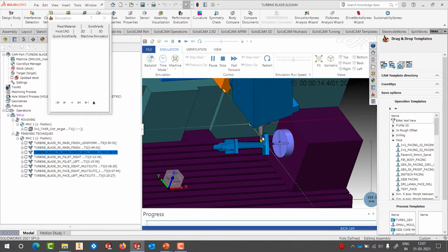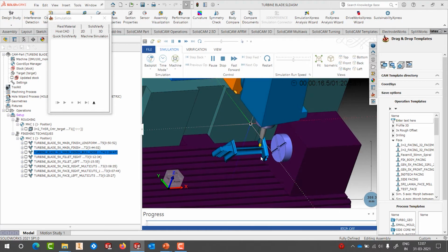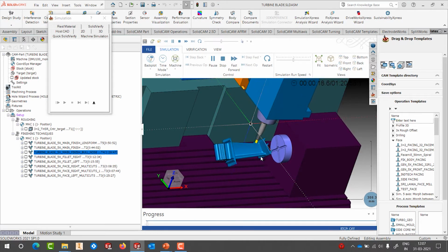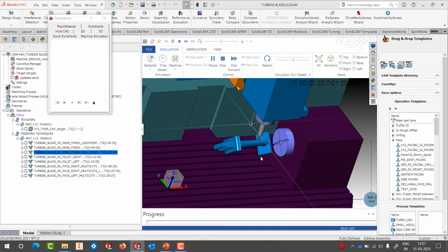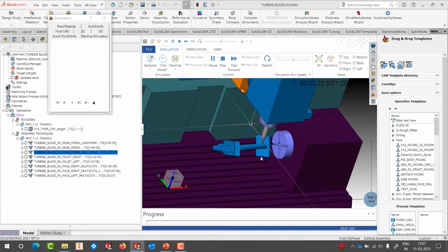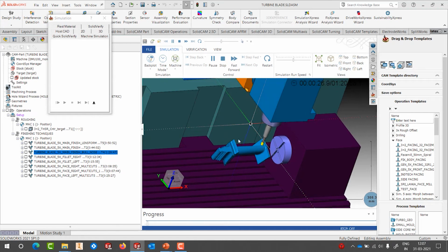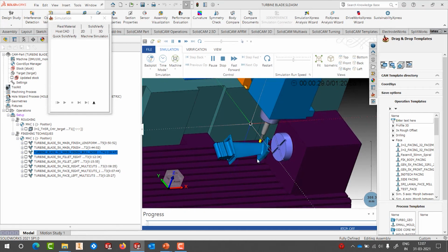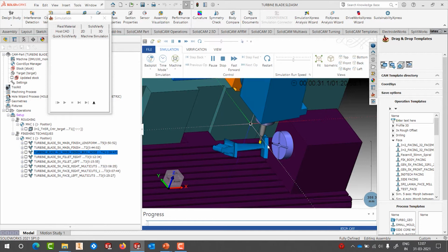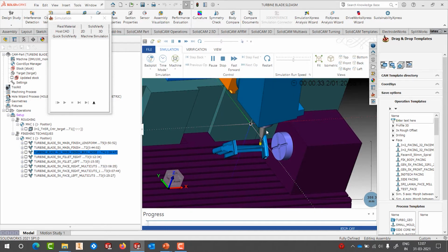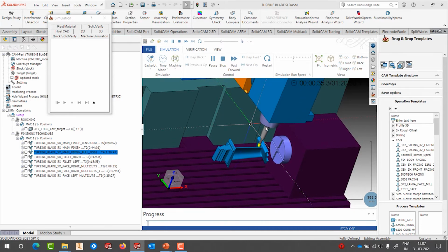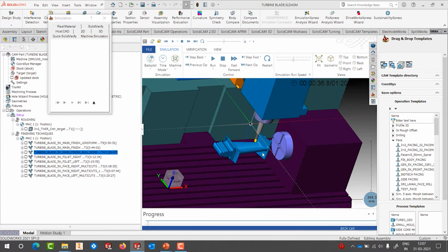And you can see that because the surface is not straight, it's a tilted surface, SolidCAM is automatically avoiding the collision using the collision checking strategy. It tilts the tool in such a way that the holder is far away from the side surface. Right, so this was using the classic bullnose strategy.